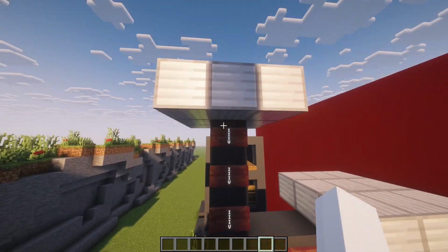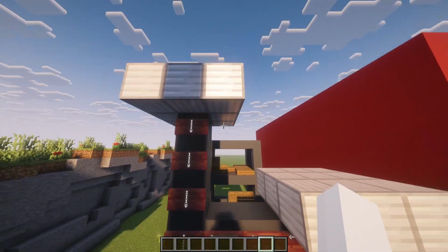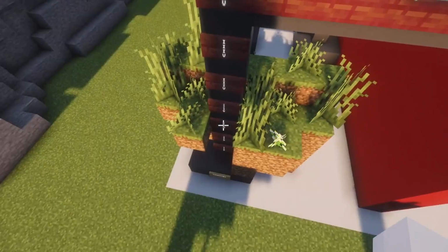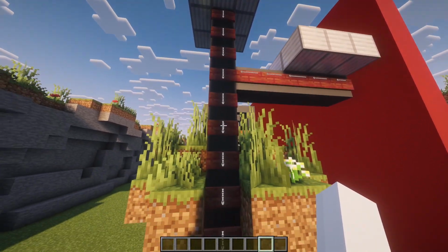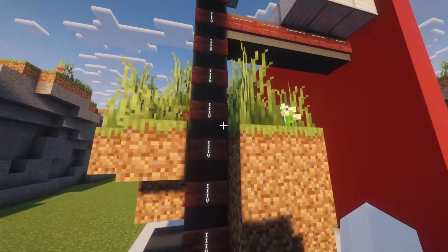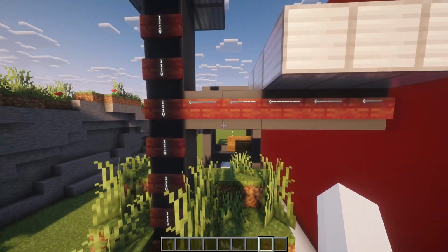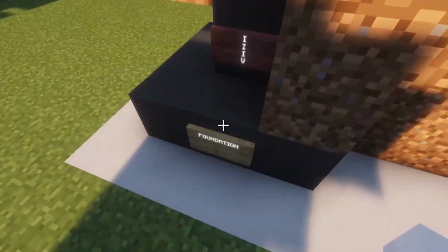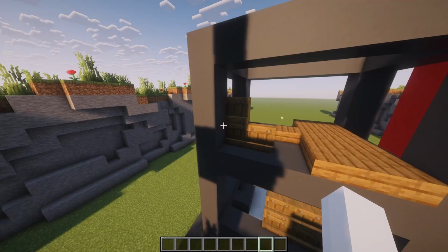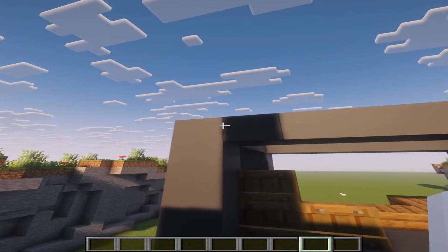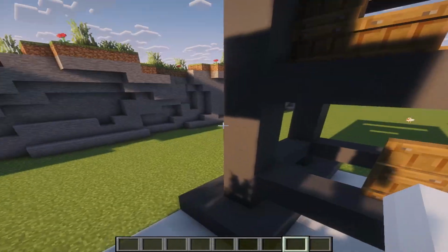So here's a piece of iron, and it's on top of this reinforced concrete. So the way that loads work is that they need to go down, right? The load is going to go from here, all the way through the column, all the way down to the foundation. And when it comes to beams, the weight that's being put down on this iron is going to move through the beam into the column and then all the way down to the foundation. And that is the basis of the system known as beams and columns. As you can see, here are the beams, here are the columns.